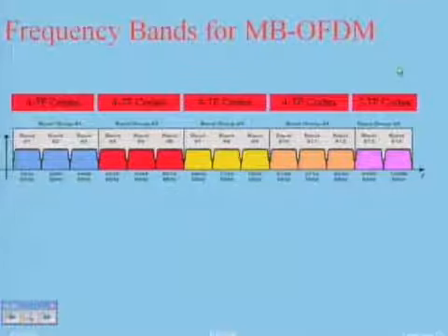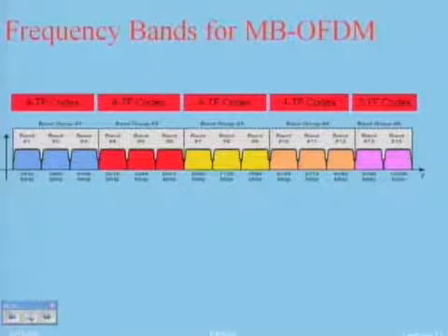And I told you about the medium access control that they are using. Medium access control in impulse radio was a time hopping technique. And then for the second one, the 2-band system, direct sequence, it was a combination of time division multiplexing, frequency division multiplexing, and code division multiplexing.